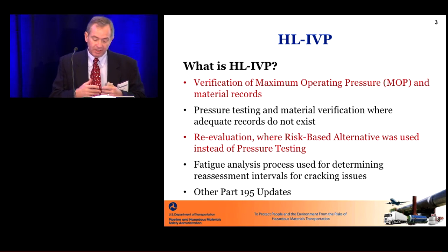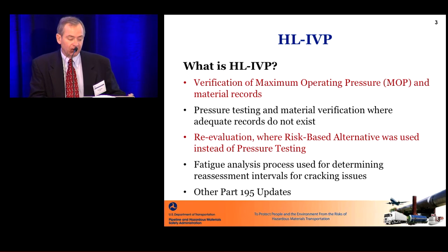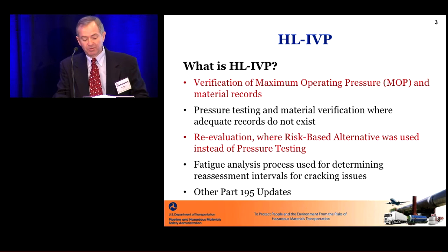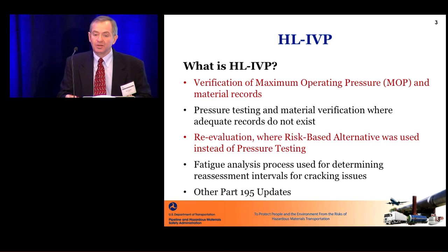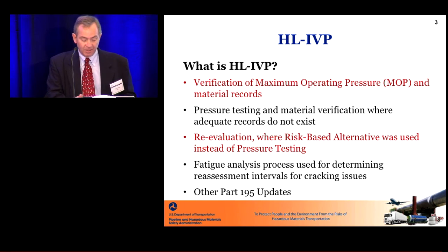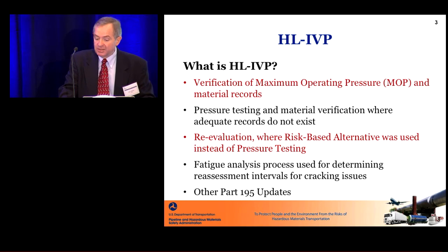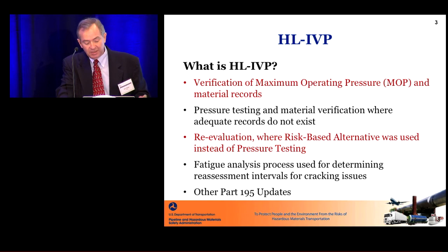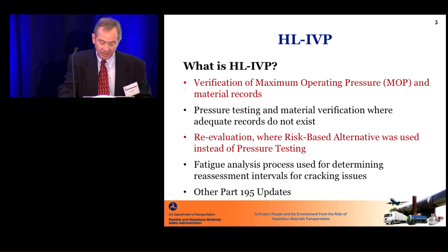And then looking at, as Robert talked about earlier, just going back and highlighting some of the gas transmission drivers, should we consider some of them for the liquid pipelines? Here are some of the mandates that we got on the gas side. You can see it requires either pressure testing or an alternative equivalent means, such as an ILI program, if the pipe has not been previously tested. Should we be doing something like that?